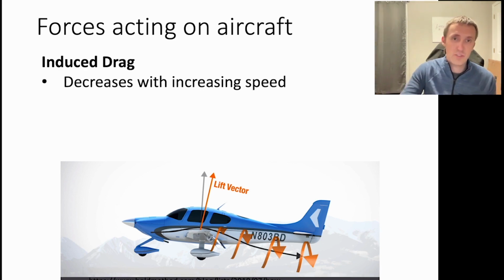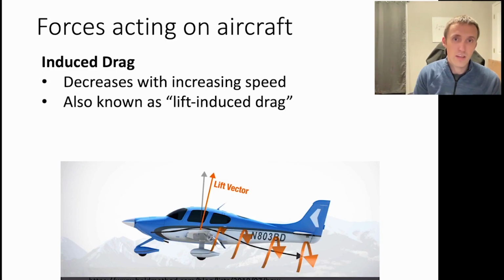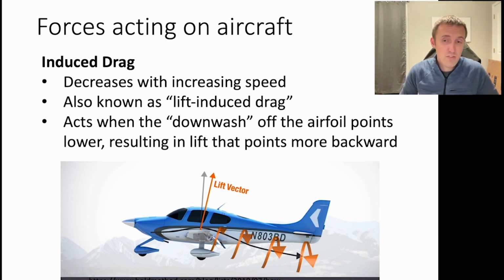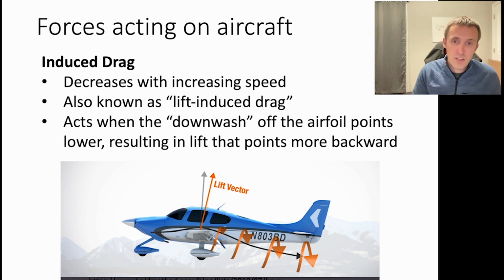Now, induced drag, so we were just talking about parasite drag. Induced drag is going to decrease with increasing speed, and it's also known as lift-induced drag, and this is actually related to what I was talking about a moment ago. This is caused when you have an angle of attack that's not horizontal relative to your direction of motion, and it acts when the downwash off the airfoil points lower. In other words, it has a higher angle with respect to the aircraft. And that results in lift that points more backwards.